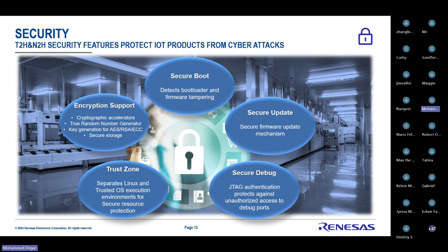And the other thing is the secure updates, right? The way the Renesas secure crypto hardware works is that decryption actually happens within the device. So you have a public-private key pair mechanism where you provide a public key for, let's say, your maintenance people or the back office to update the firmware on the device, and inside the device you have the private key. And with that public-private key pair mechanism, the actual decryption will happen within the hardware, living highly secure.